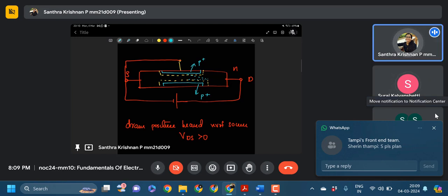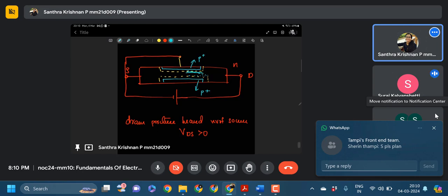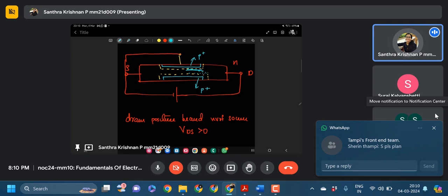Yeah, but the depletion region, if you say depletion region, it essentially means that there are no charge carriers in that area, right? Nothing is moving in that area, everything is arrested. So when the bulk of electrons starts moving from S to D, the concept of depletion region starts losing its value. There are excessive charge carriers flowing towards this part, right? That is why we say that towards this end, the depletion region starts narrowing. That region gets filled with carriers.